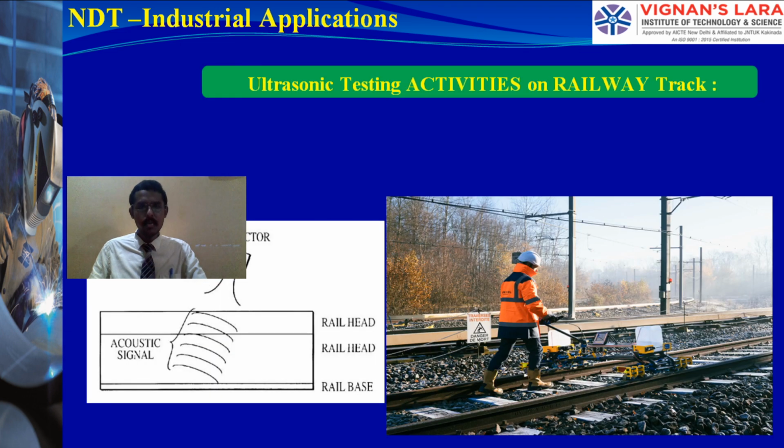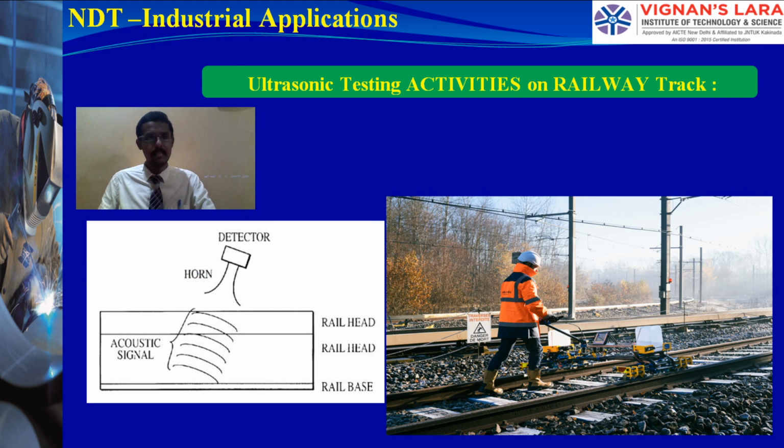See, a few images I have added here for our understanding of the theory part. This is the procedure of the horn we have, and we are supplying the ultrasonic waves inside the specimen, and it comes back, and we detect. So here in this picture, on the right side, an employee is doing an in-service inspection through the ultrasonic method.